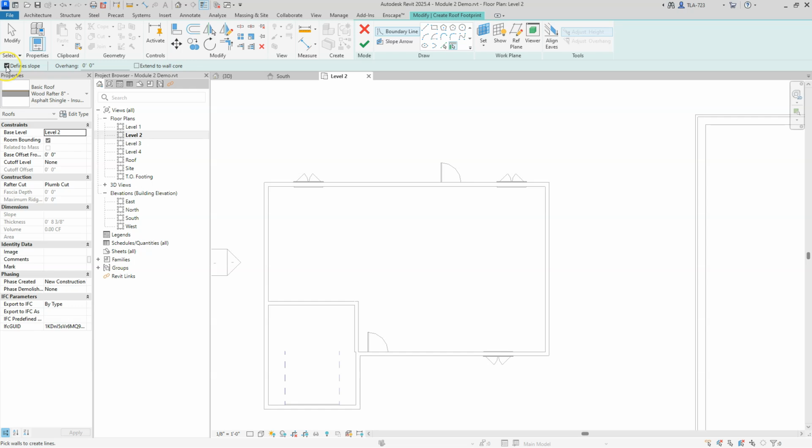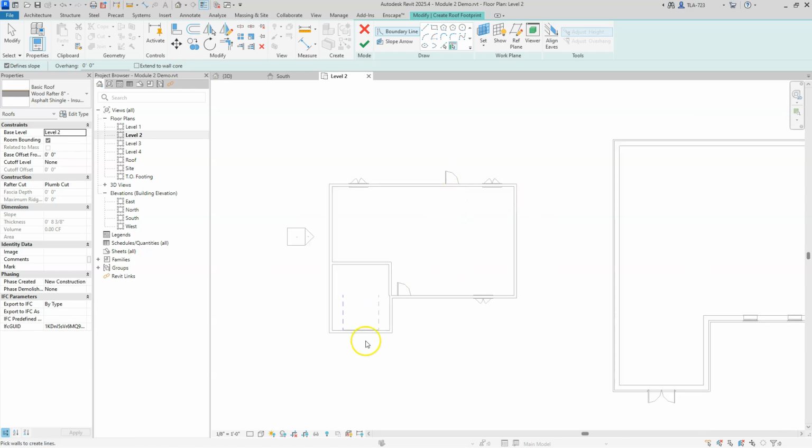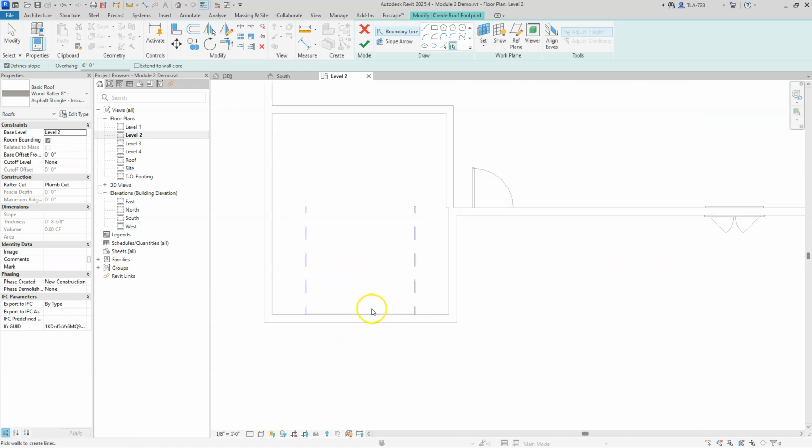And then we also want to define slope if the edge of the roof we're creating is a sloping edge. Okay, so what do I mean by that? Well, you know through our discussions in construction theory classes that any roof is either going to have an eave going across there where you would see a gutter. That's a horizontal eave. Or if you have a gable end, you're going to have a sloping edge, right? So in other words, we might put a gable. In fact, we will do that later right here. We're going to put a gable right here.